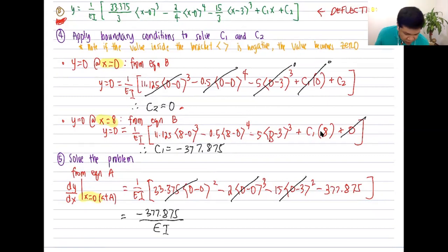So what is the unit of measurement over here? Since I didn't convert any value of my forces, please remember that if I have slope over here, your numerator would be force. Okay? So I didn't convert anything. Force times length squared. Okay? Why? Because EI is actually, E is megapascals or a unit of pressure times I, which is length to the fourth, which will leave us with force times length squared.